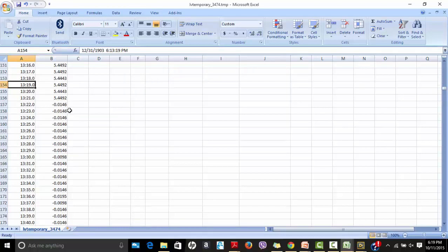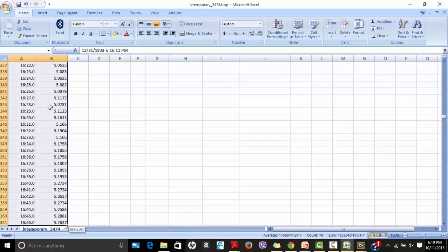So 157. Now I will go and search for a VOL to VOH transition. As I can see, at line number 326 it is minus 0.01, which is roughly a VOL value. Let me monitor it until it reaches 5.45. Let me see where it reaches 5.45, and the closest value for 5.45 is reached at line number 457.